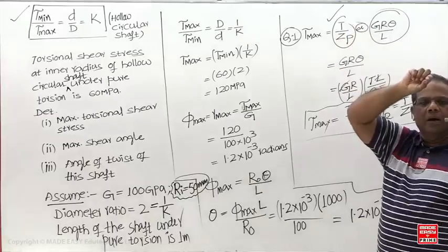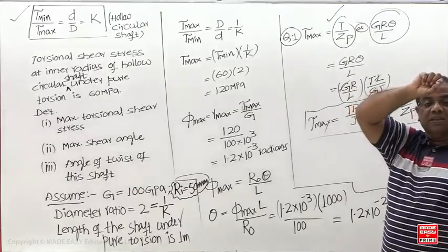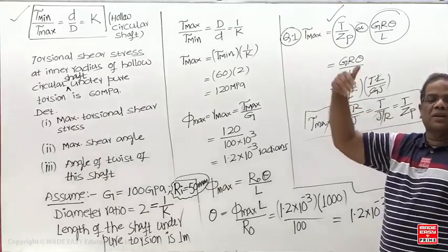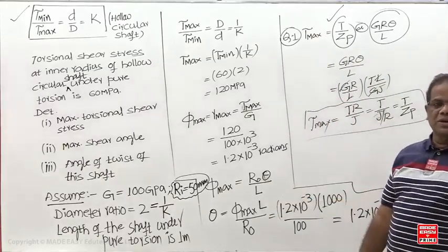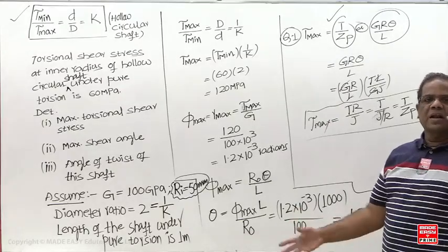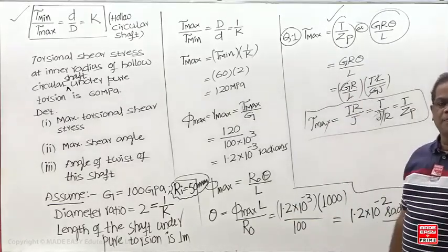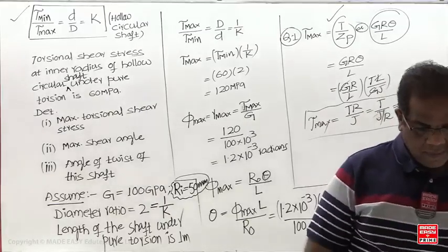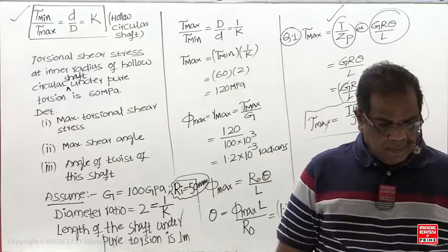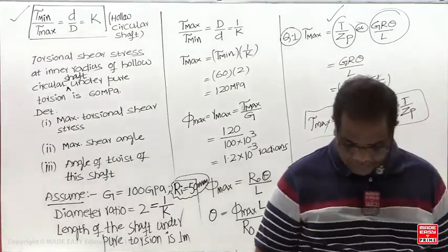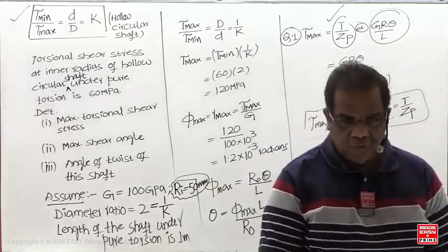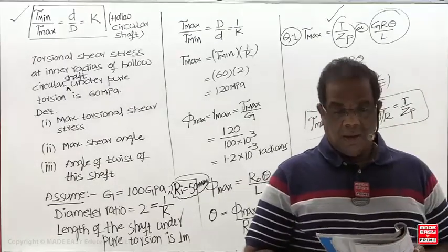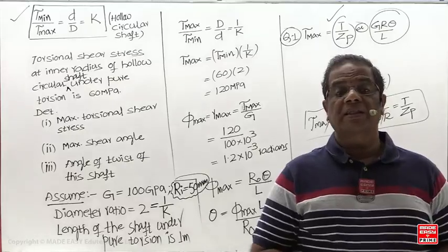Directly what now? Stress on the cross section is directly proportional to the corresponding load, inversely proportional to the cross sectional dimensions. In both the cases, load is same, diameter same. So directly the answer is C. Question number 2, the answer is A. But option D, when is option D correct now?